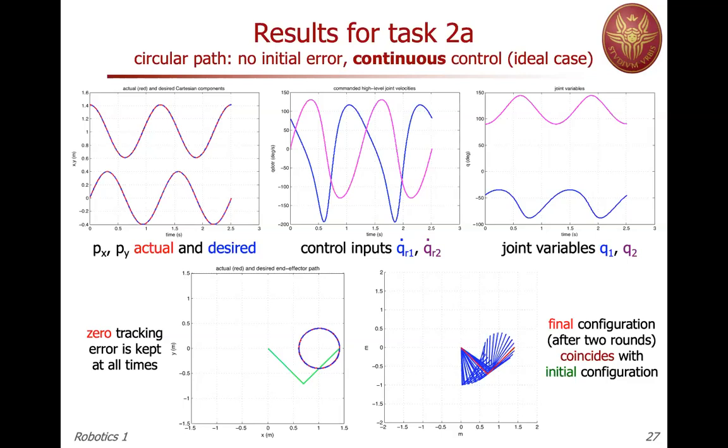Okay, why not? Because we have a nonlinear mapping between the joint space and the Cartesian space. These are trigonometric functions, sine and cosine, but of an argument which is also trigonometric. So as a whole, it's a nonlinear behavior. They are periodic because the system is non-redundant, so we are tracing the same motion on and on, so we are periodic in time. In fact, we are not encountering any singularities, so periodicity is automatic, but the behavior is non-sinusoidal.